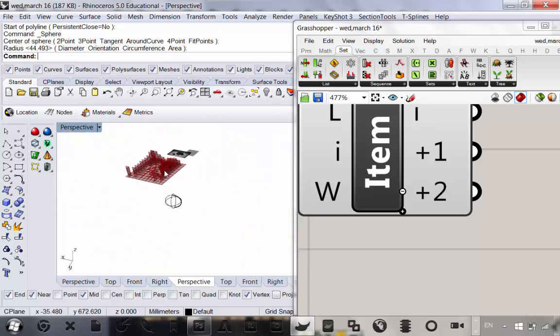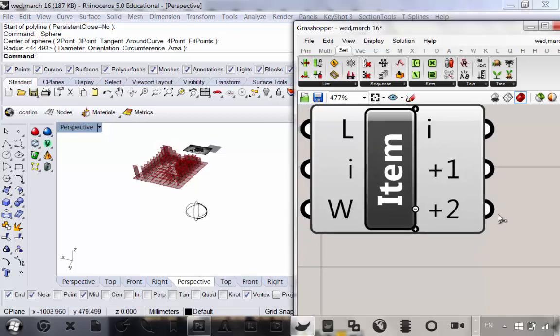So what I want to do is take all these west faces and twist them towards this sun here. Then I'm going to loft that geometry to create these twisted spires that are facing wherever this object is.